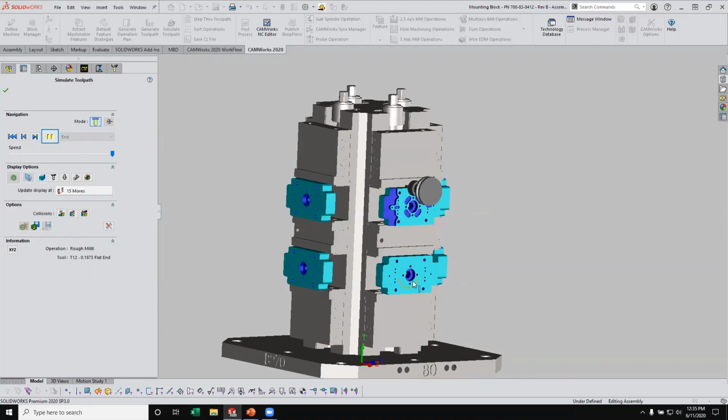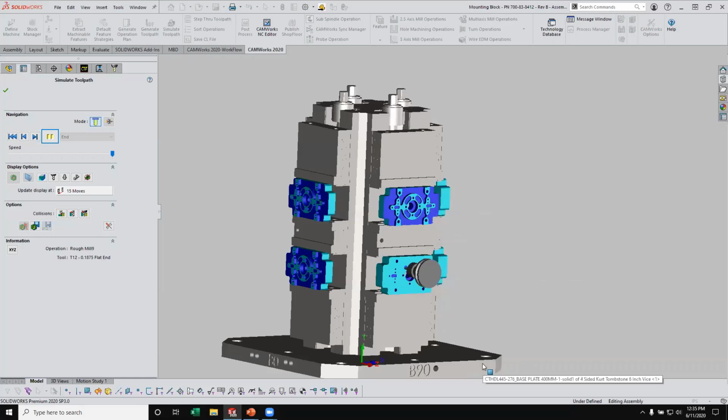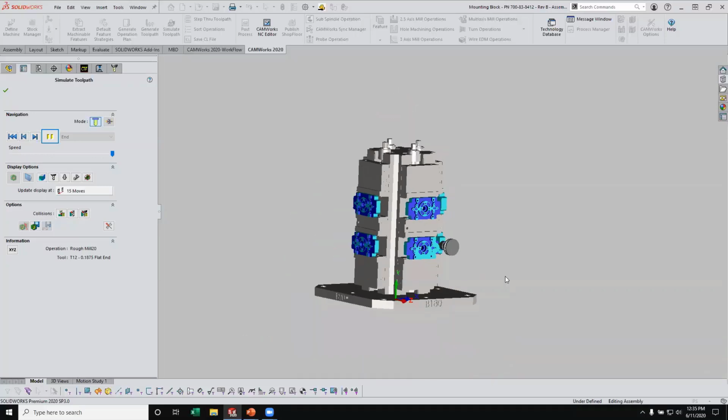And you can see the rotations here. You can see it milling around. Right now it's doing B0. If it was real fast rocking back and forth, that was the different rotations. You can see it just indexed there to B90. It's milling. I'll mill all around these parts here.